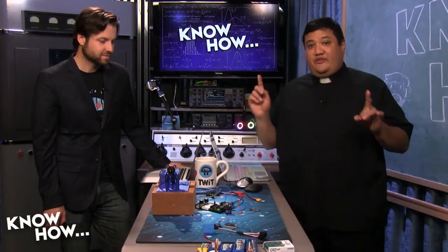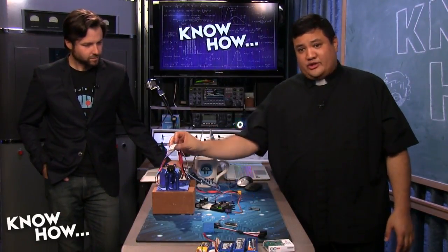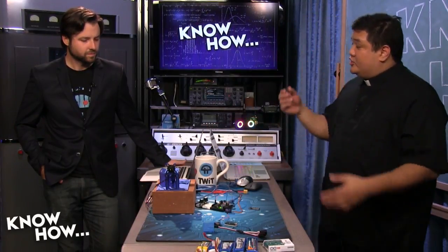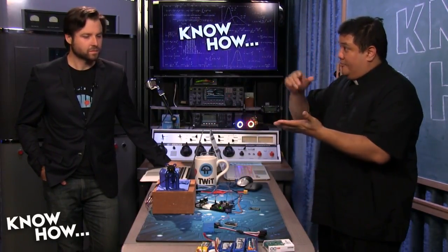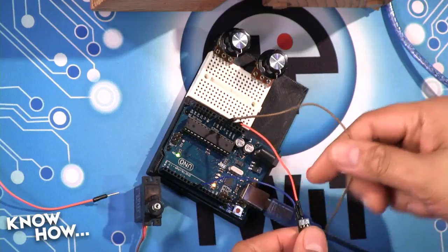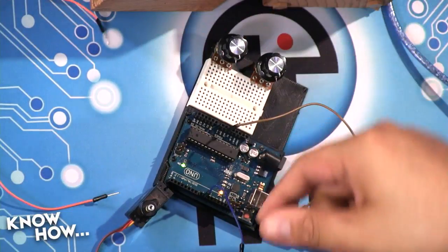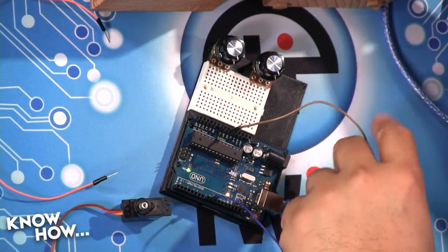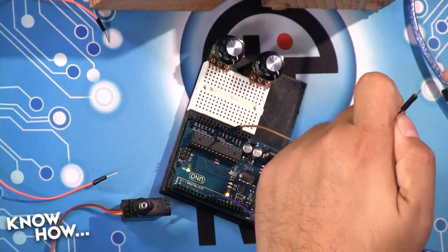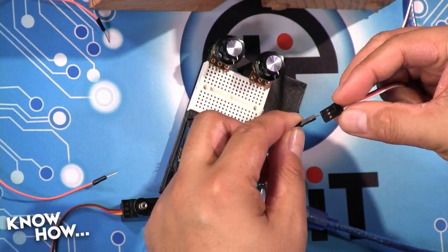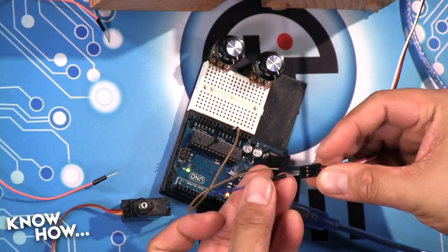Okay. Now, here's the fun thing. We just showed you how to do that with a servo, but an electronic speed controller, like the one we have hooked up to this motor, works exactly the same. It just looks for that positional data, the PWM pulse, to tell it where it should be set. So theoretically, I don't need power, because power is going to come from that battery. But I can connect this to the exact same pins, ground and signal. So this brown one's going to go to black, and the signal pin's going to go to white.